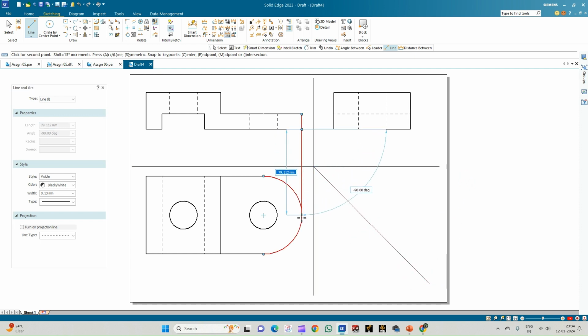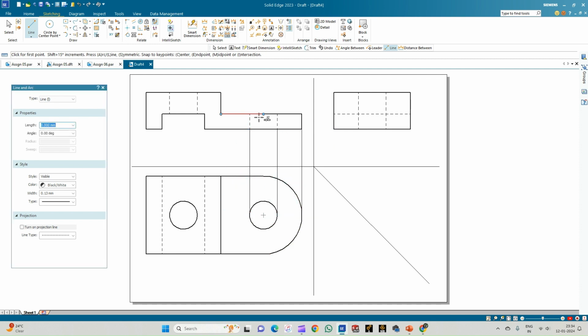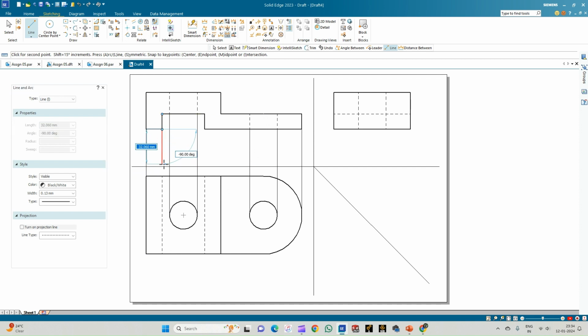So let me complete the front and the top views. So you can just see that the circle will not be visible in the front view. So the dotted line indicates it is a circular hole, through hole. So that is why the circular hole, which is a through hole, is shown by dotted lines throughout the thickness of this rib. Okay, so this is the same even for the hole on the rectangular face also. And this is the lower portion of the rib which is not seen on the top, so that is why it is dotted line here.